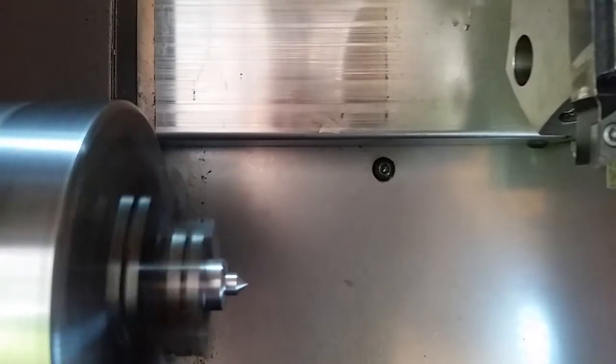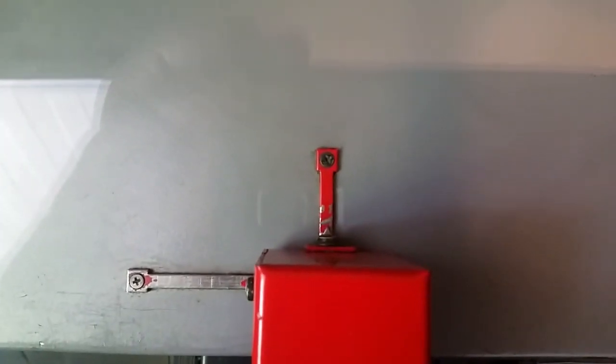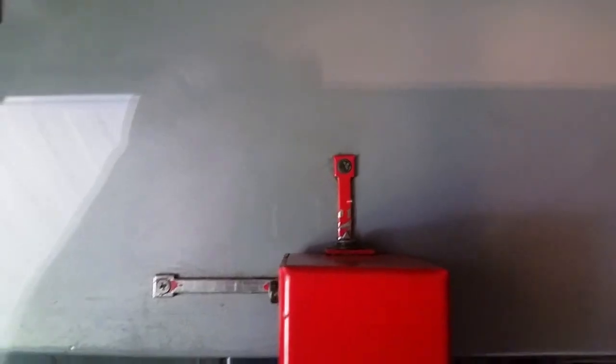So at the end of the program you can see that the machine actually goes all the way up to the reference position again, and this is just the way I like it. I want to leave the machine so that it's quick to reference, because the Emco has this oddity that it references on an indicator on the stepper drivers once per turn. So if you position them more than like 10 millimeters away, they will actually not reference to the correct position at all in the machine.